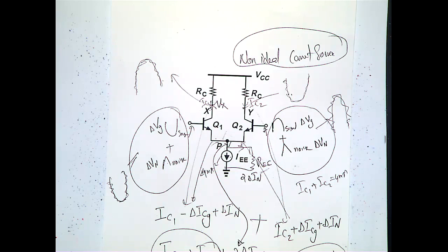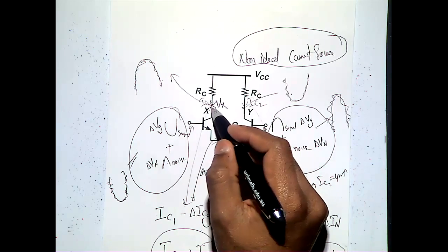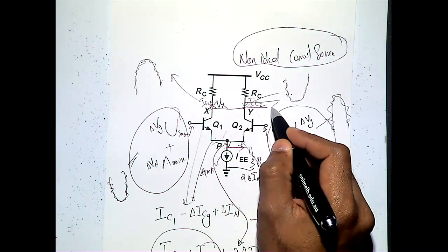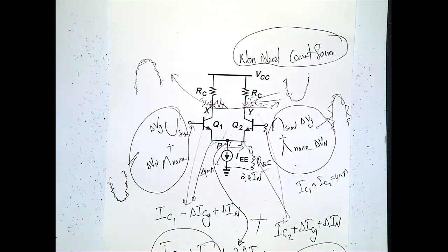And then, now we are still happy. Why? Because then you will say, I will take the voltage between Vx and Vy. I will be taking these 2 points. Then my signal is clean. When you have this situation, you have solved this issue. And then you said, now we can make the chip, the input of the differential amplifier. You are going to design a chip.